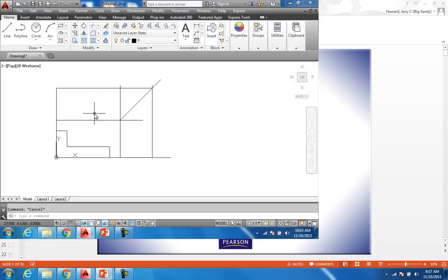So at this point, I'm going to shoot this line up right there as well to get my top view. So basically, my top view, I've got everything set up for that. So this is just the overall size of my top view, and I transfer the depth of it up to here. Now my right side view, I'm just going to take right there, shoot this over here to there, and we've got it. We've got the gist of it laid out. Let's come through and trim up these lines I don't need. So basically you've got your top, front, and your right side sitting there.